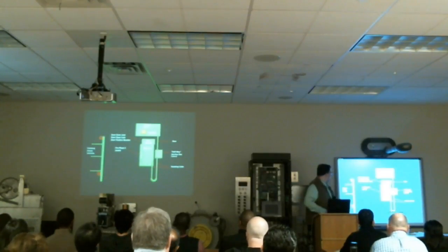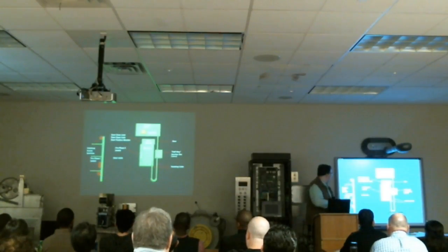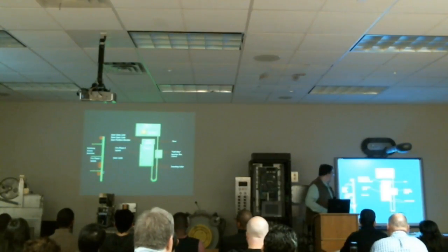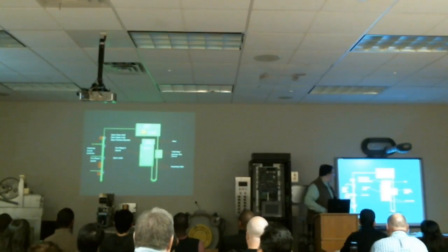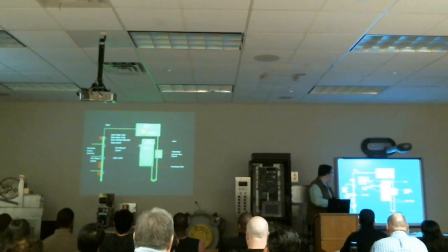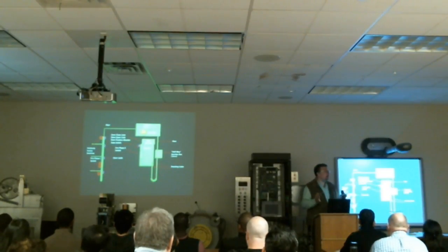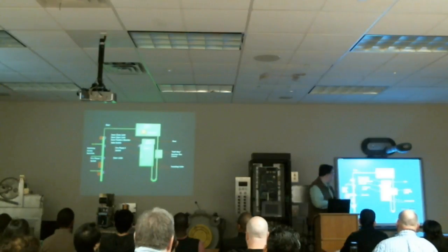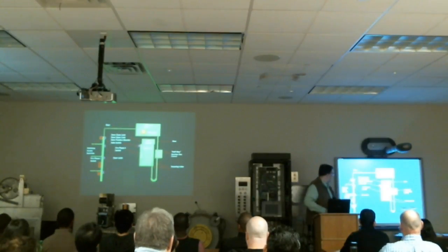What else do we need? Well, we also need to know, for example, fire phase 1. So we have to know when we're in phase 1 operation in order to be able to go into phase 2. We also need to know the door locks for each floor, the statuses, and the gate switch. So we have to know if the gate in the car is closed or open. This is the riser, where the wires from the shaft go back up to the machine room. And the wiring again depends.